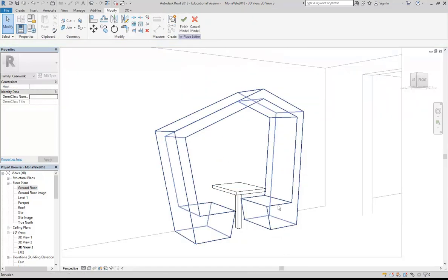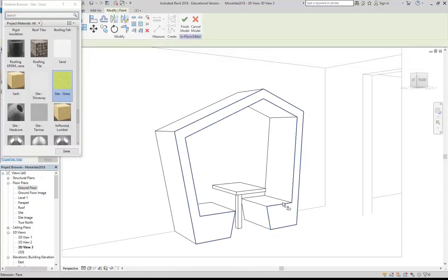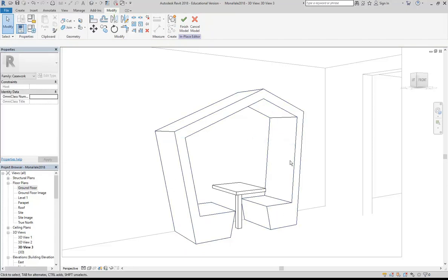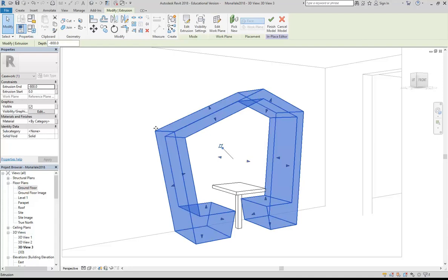So now notice I can select these things. Now here I could use paint. You can see I can then select all the different faces, but that's a lot of work. There are lots of faces there. It's much easier just to select the object and then come over here and you've got the material right there. What if you want to have different, not just those two materials? Yeah, then you would use paint. That's the time you use paint.